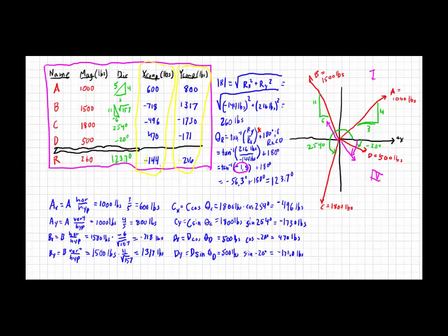So what we're looking for is a force, such as the opposite of this resultant, that would make this system come into equilibrium. So we can find the resultant and then simply take the opposite of it. Or we can simply assume that the resultant is going to be 0 and find the force by placing it in the table here without values known, and then find the values. That's what's going to be next.